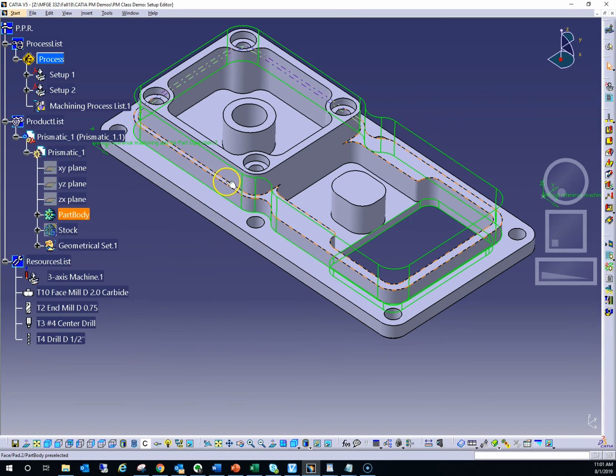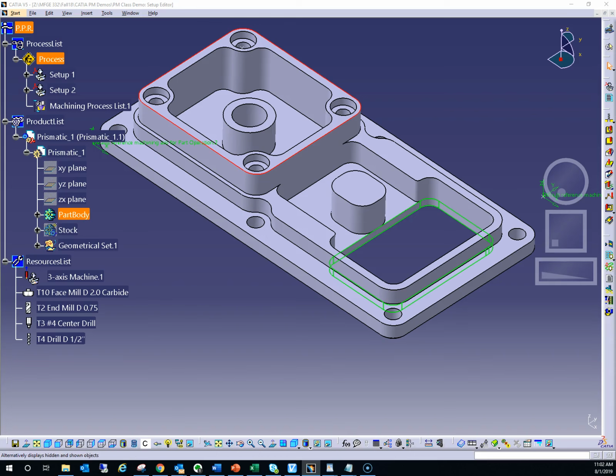However, there is this ledge here that goes around this region that we didn't get using this first profiling operation. So we need one final profiling operation to run around this region here, to get the correct surface that we need. So that would look something like this.